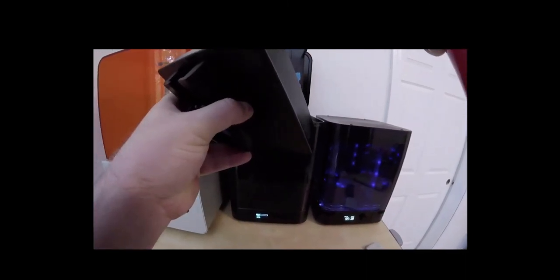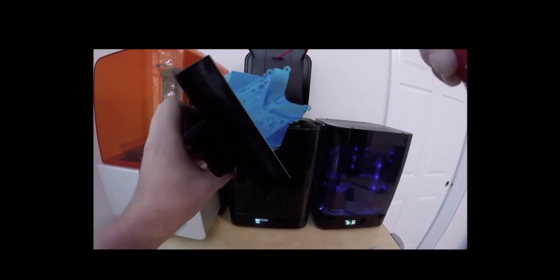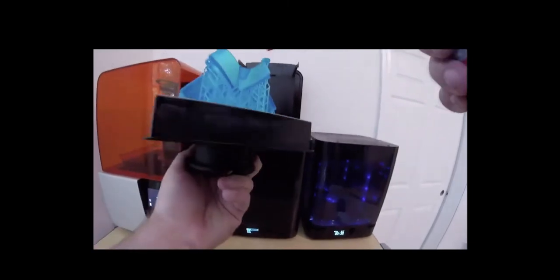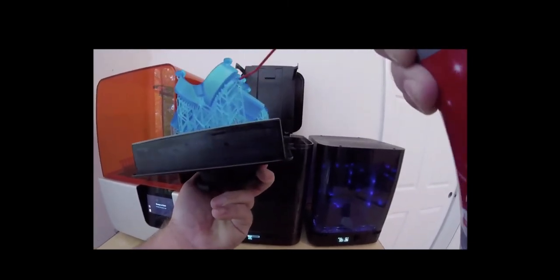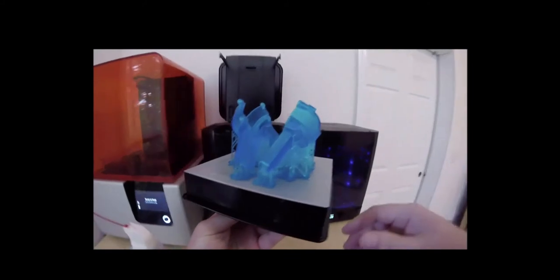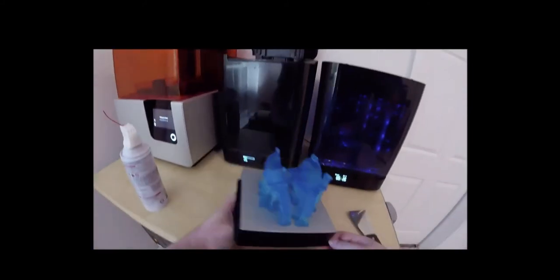Any tight corners like this can sort of trap a little alcohol, and you can see it probably spraying out of there right now. So I just like to go around all these sections, just make sure I'm not leaving any areas where there's liquid alcohol and resin, because once that goes into Form Cure, that resin and alcohol will actually cure in place. So we want to make sure we get it off there and it's dry first.